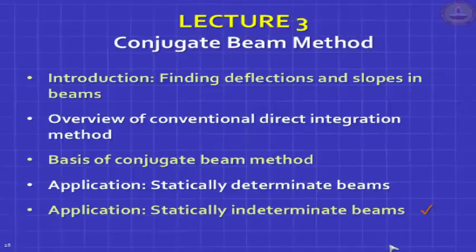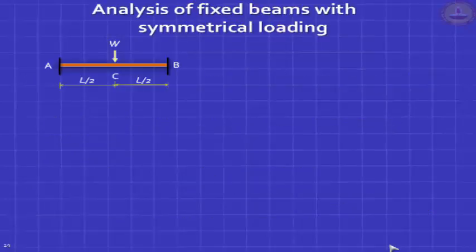Now we'll do something very, very interesting. Maybe we're a little ahead of the time. In the third semester normally you don't teach all this. Fifth semester also they may not know. Seventh they'll know. But you can use the same conjugate beam method to solve even indeterminate problems. Remember the fixed beam became free. So let's see how that works.